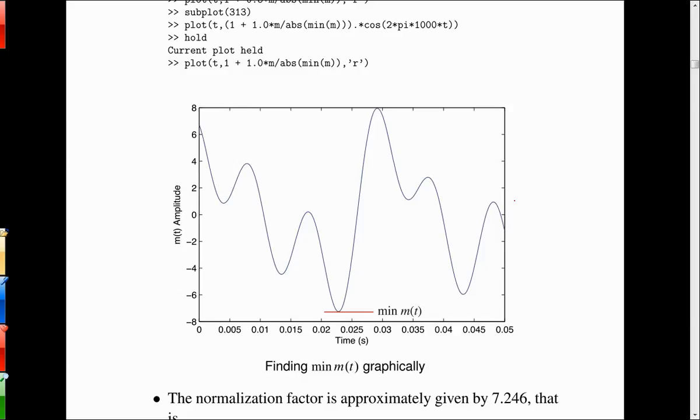And I know it's not something you talked about in electronics, but you can make a variable gain amplifier where the voltage can be used to control the gain, and then you can have a power sensor on the output of the amplifier that just rectifies the output, creates a DC bias, and that becomes a set voltage that goes through a differencing circuit or a feedback amplifier, and then basically is like automatically raising and lowering the gain of the amplifier to keep it at a constant level.